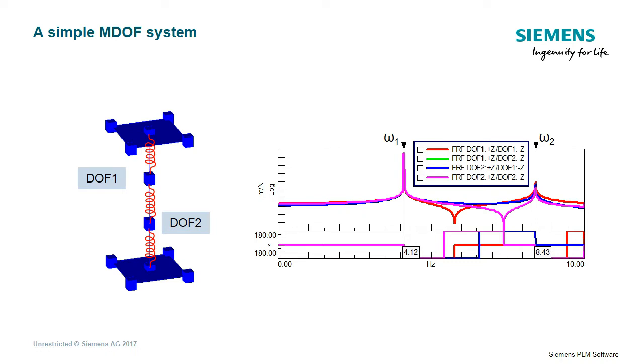To properly discuss this one, we need to add an extra degree of freedom to our system. We have now two masses connected by a spring. The system now has 2 degrees of freedom, which are the responses of the two masses. If we now calculate the frequency response function, we can immediately identify 2 resonances at different frequencies. At this point, the definition of mode shape is extremely simple.